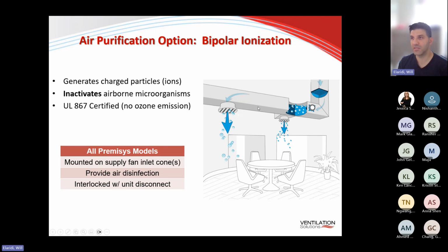So the concept behind this is simply the needle point ionization: as the air passes through it, it'll electrically charge these particles, negative or positive ions. And as these ions get injected into the space, they'll find other particles to attach itself to in order to neutralize its electrical charge. Once it finds those other particles, such as water particles or any other particles, it'll attach itself to it and then basically drop down to the floor or the table, but mainly away from the breathing zone. So it relies on the particles shifting from the breathing zone all the way to the floor, which you can pretty much vacuum up and dispose of.